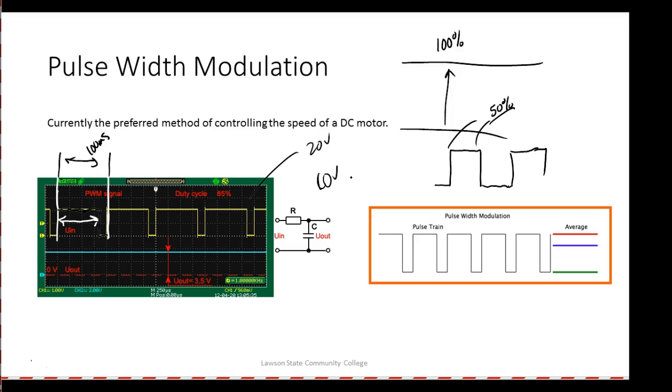So if I can get these electronic devices and switch them off and on, right, you understand, an SCR can't work off DC, an SCR has got to work off AC. So I got to put AC across the SCR, and then it produces DC when you turn it on or off. This guy I can control with transistors, right, or different types of devices. Because what we're doing now, we're turning the transistors wide open, or we're turning the transistors off. When you turn them wide open, they drop very little voltage, right? You understand. When you turn them off, they have no current.